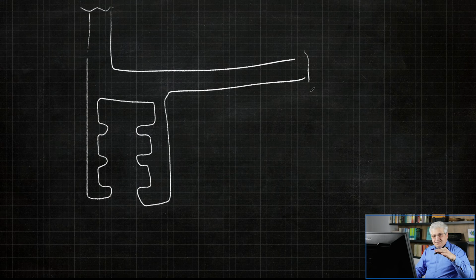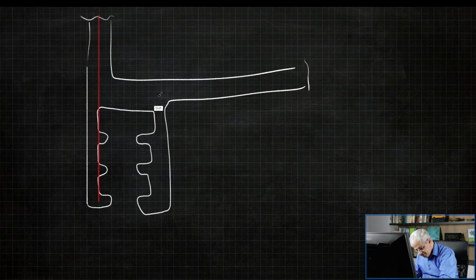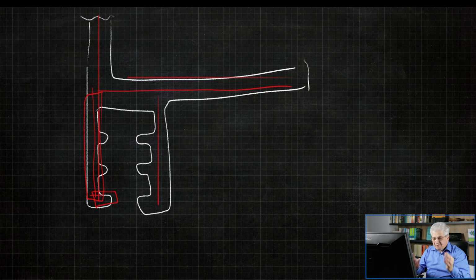In the 1999 Eurocode for aluminium, there is also an explanation how you have to simplify the cross sections. And if not in Eurocode, then there is this design book for aluminium structures. Then there are also some explanations with pictures. And in this way, we will draw such a line. So we will simplify it. Not draw everything, but we will draw only a line with one thickness, and this will be classified as a part, and this also one, but not all these details will be used in the classification. So you have to simplify it, and therefore it's also very good to split the input of the polyline and the input of this thin wall representation.